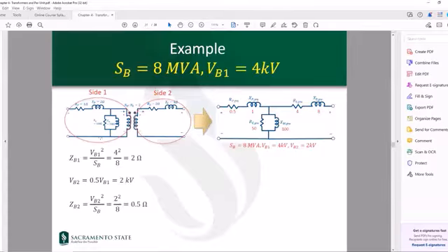So this means that we need to consider the different areas in terms of the voltage levels. Like in this example, there's a single phase transformer. Obviously, there's side one, and there's side two. Each side has its own base. So if you choose the voltage base on side two, then the voltage base on side one would be determined based on the voltage base that you chose on side two, or the other way around. If you choose the voltage base on side one, then you have to change side two's voltage base based on side one's voltage base and the turns ratio of the transformer.